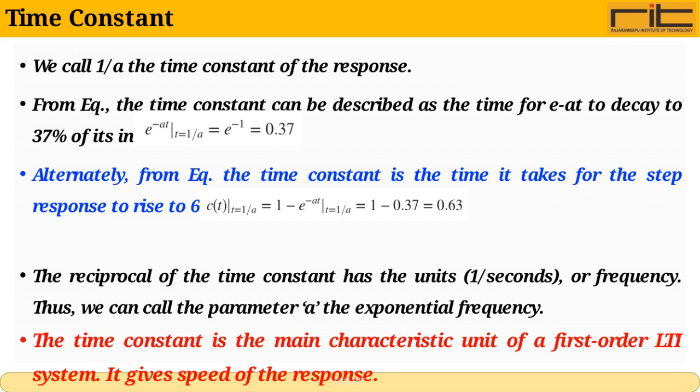Another way to look at it is through the step response. The time constant is the time required for the output to reach 63% of its final steady state value. Since the reciprocal of the time constant has units of 1 over seconds, which corresponds to frequency, we often refer to a as the exponential frequency. Understanding the time constant is critical because it characterizes the speed of response for a first-order linear time invariant system, making it a fundamental parameter in analyzing system dynamics.